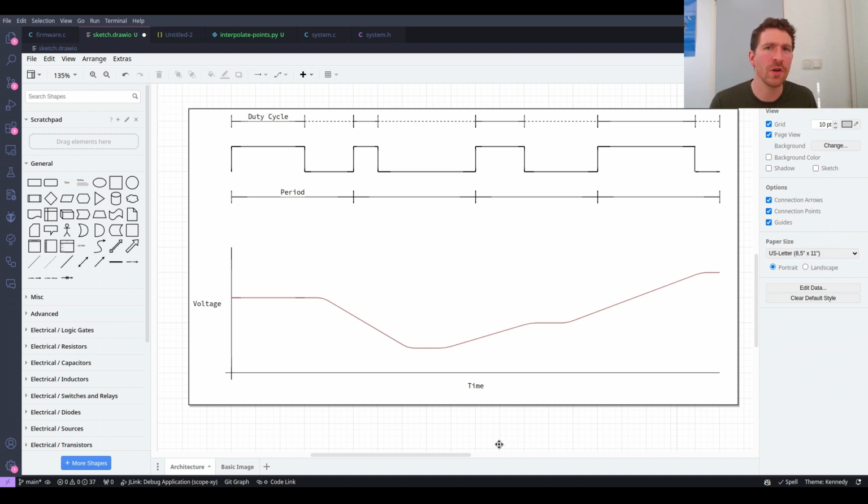And this is not a particularly good digital to analog converter. There's a lot of loss in this. And actually, when you just have a single RC filter stage, that's not a very good filter, right? It still leaves in a lot of high frequency components. It doesn't really just take out everything. It sort of just turns the volume knob on those down a little bit. And the higher the frequencies, the more it turns the knob down.